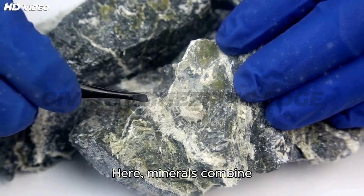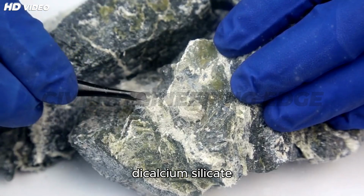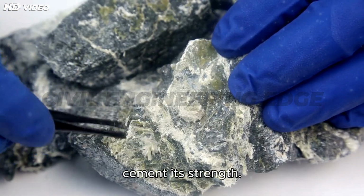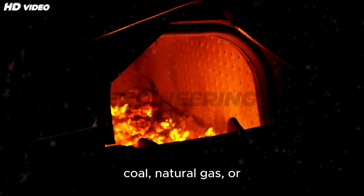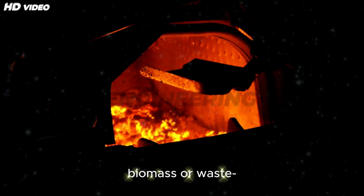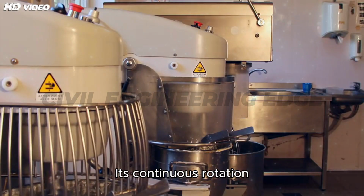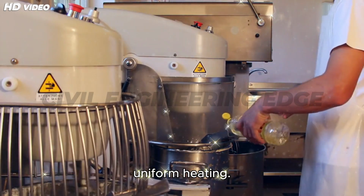Here, minerals combine to form tricalcium silicate (C3S), dicalcium silicate (C2S), and other compounds that give cement its strength. The kiln is fired by coal, natural gas, or alternative fuels like biomass or waste-derived energy. Its continuous rotation ensures the raw meal mixes thoroughly and undergoes uniform heating.